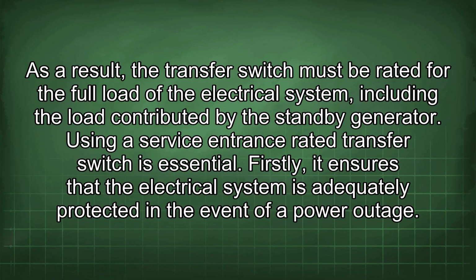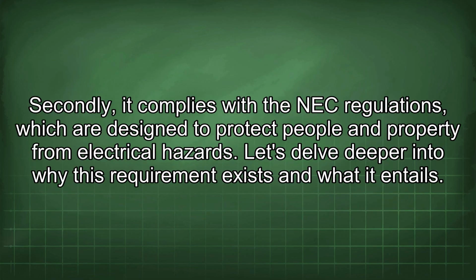Using a service entrance rated transfer switch is essential. Firstly, it ensures that the electrical system is adequately protected in the event of a power outage. Secondly, it complies with the NEC regulations, which are designed to protect people and property from electrical hazards. Let's delve deeper into why this requirement exists and what it entails.